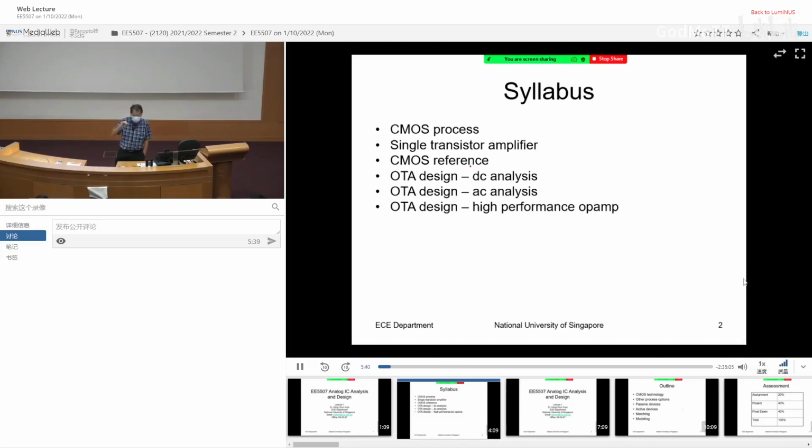So in general purpose, you can do it, but you sacrifice a lot of things. Also it can drive any resistance that you want; even if you use 100 ohm, it works. But the good thing about IC design is that you customize your own operational amplifier, and you don't have to deal with very low resistance, which means a lot of the time, the buffer stage is not needed.